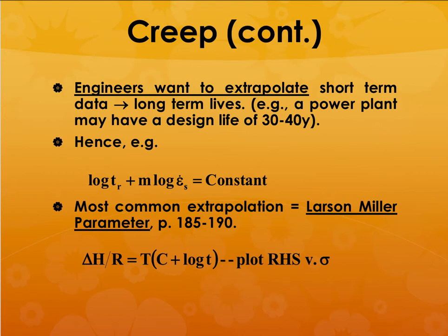So where is all this important? Say for example, if you have a power plant, you have a design life of 30 to 40 years. What we do is we test these materials and we get short-term data, and based on that we extrapolate to see if your component is going to last for that long or not. The most common extrapolation is the Larsen-Miller parameter.